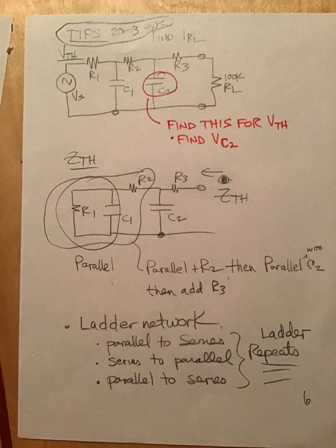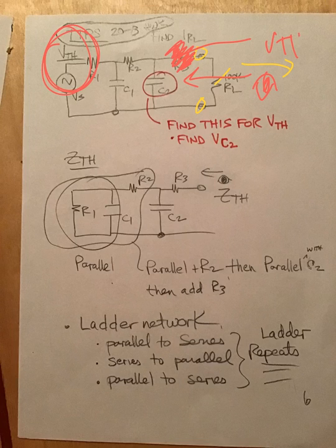Tips, okay? Tips. Let me see what I want to talk about here first. Okay, so here's a typical circuit. You're going to remove this load and take it away. That's going to leave a gap at the yellow dots, and you're going to look into the red arrow with your eyeball. Don't forget, when there's a resistor, a capacitor, or an inductor up here for Thevenin, this part does absolutely nothing. So the voltage that you're after for Thevenin is that capacitor voltage right there. That's what you're interested in.